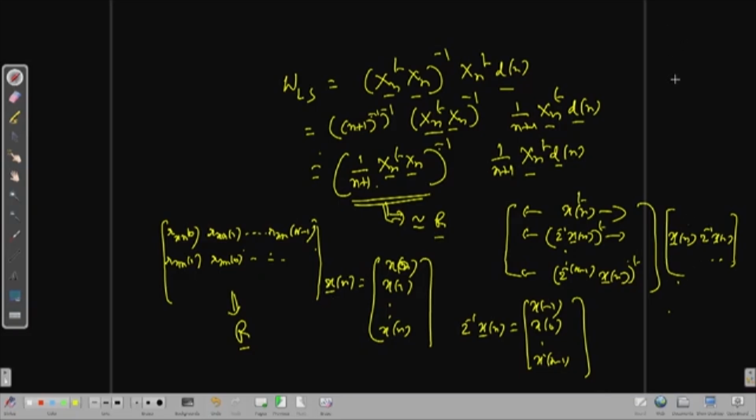And here is xn transpose dn. If you have got dn, the xn transpose dn vector, take a transpose of it, then dn. So x0 d0, x1 d1, xn dn. So you are multiplying samples of both at a gap of 0. So it is a cross correlation with gap 0. And then dividing by n plus 1, so you are averaging. So cross correlation with gap 0.